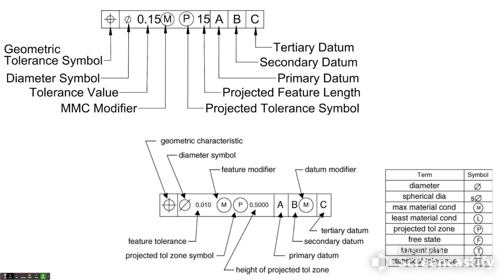So if you think about it, if this is just a flat plate, of course we are going to want a datum for both sides, or both side walls, of the plate, and then another datum for the overall thickness of the plate. That would give us a relationship with A, B, and C there, where we spell out the datum.